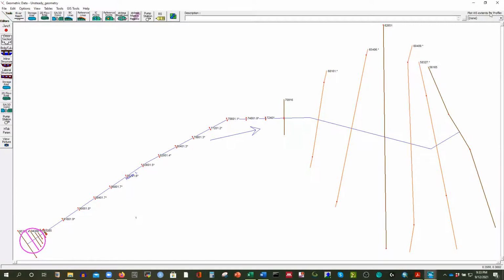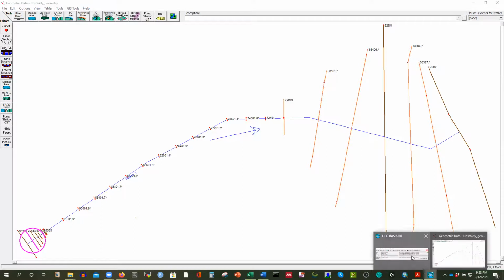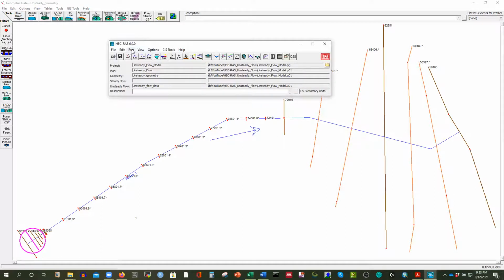And last, I'm going to show the effect of time step. That is what I was trying to say, what will be your time step. At the same time, you have to reduce the time step and improve the accuracy of your model prediction. So for this condition, we have our observed data, and we'll check with our observed data. I'm not going to do that here right now. I'll do it for the sediment transport model. We'll test because we have our observation sediment density, and we'll check if our model is working or not. That's why we'll calibrate our sediment transport model, because we have our observation data.